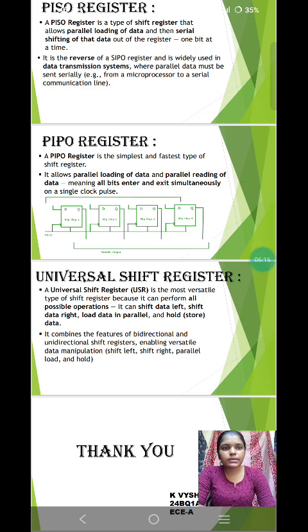Kirchhoff's laws. These fundamental circuit laws, along with Ohm's law, are used to solve complex networks. Kirchhoff's current law: the sum of currents entering a node is equal to the sum of currents leaving it. Kirchhoff's voltage law: the sum of voltage drops and rises in any closed loop of a circuit is 0.